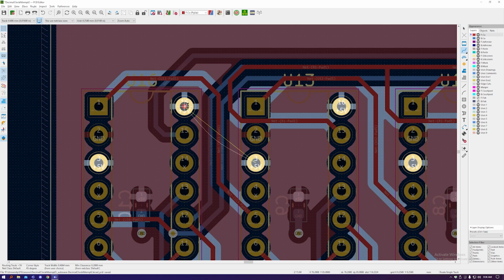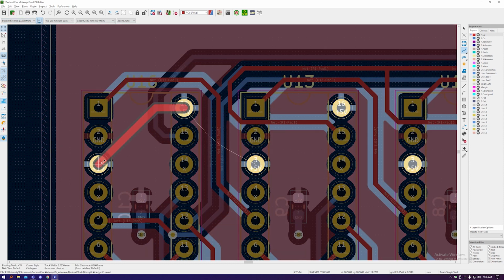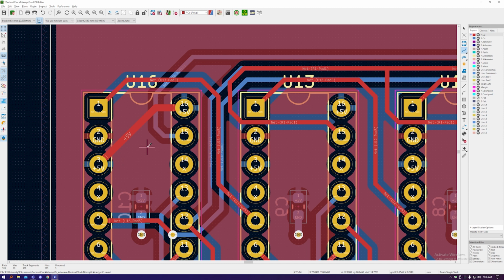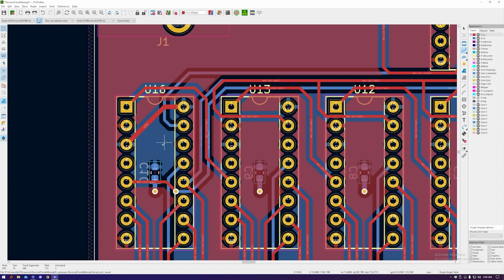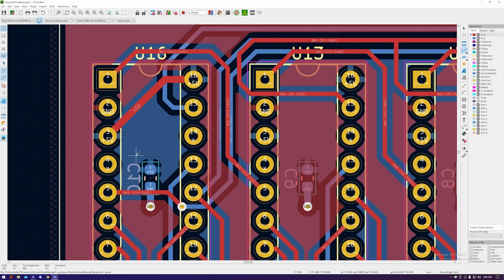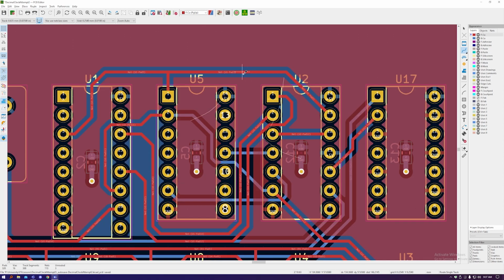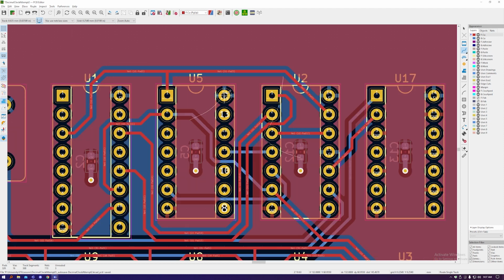So we'll go on the front here, and it's power, so I need to change to 25mm. Then just drop down like that. And that's fixed the issue. Now it's created a big area here that isn't grounded, but it looks like that's not an issue, so that's fine. Now we're just going to do the same with the other ones. Because they're all issues with the fills, they're all power, so we're going to stick with the 25mm traces for all of them.